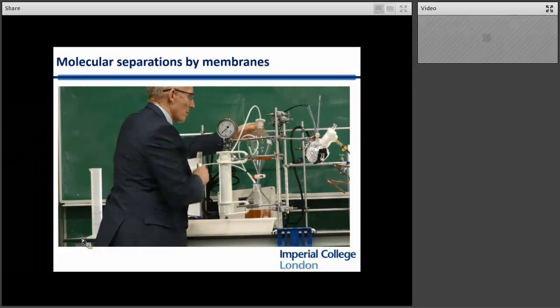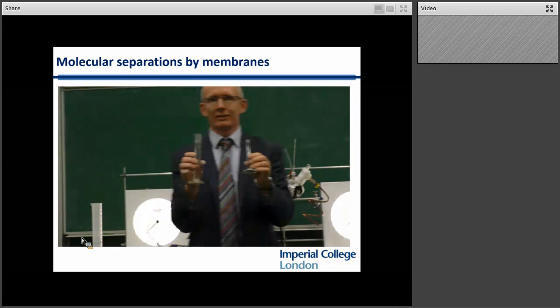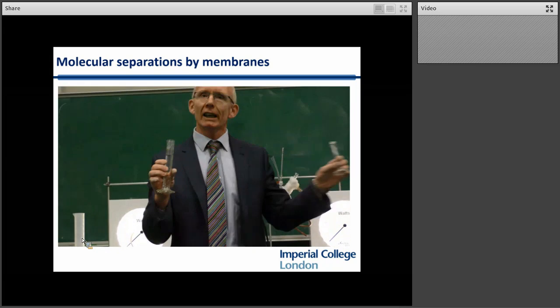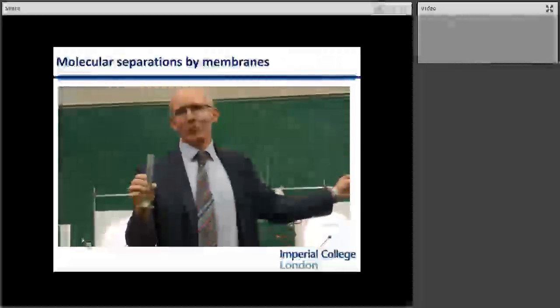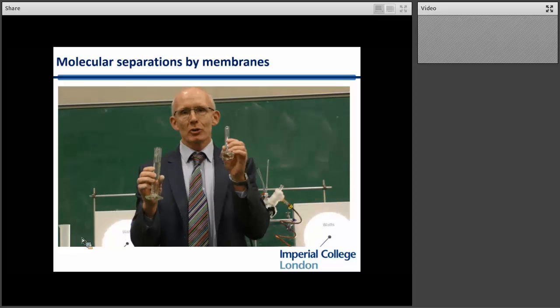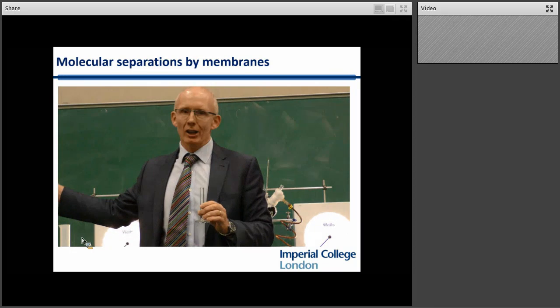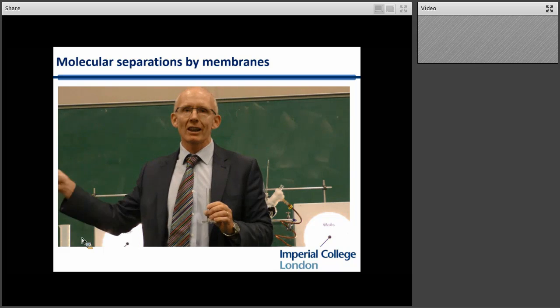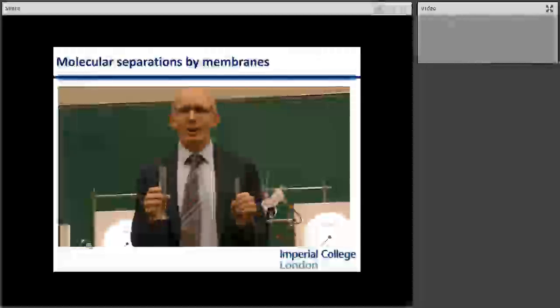In the membrane experiment, I've generated over 50 mils of water. So what a comparison. Here, cycling for a minute at 250 watts, wearing myself out, I've produced 2 mils of water. Here, cycling for a minute, running at only 50 watts, very sedately, I've produced over 50 mils of water. And that is why membrane technology is far more effective than thermal techniques for purifying water.